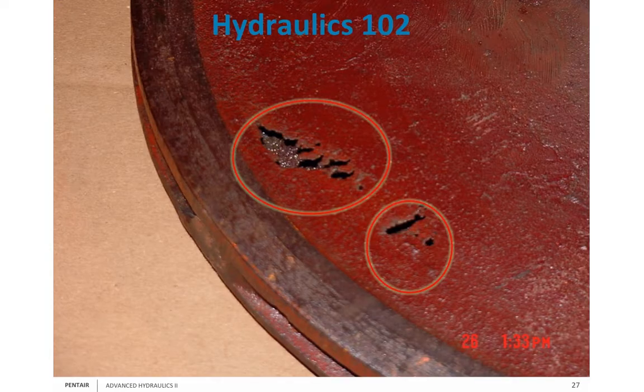Okay? So, cavitation damage here, you can see it's inside those two orange circles. And, of course, you can see it ate right through this impeller. This impeller, by the way, is an 18-inch impeller. It is $2,000 list price. And when we told the customer, look, if you would just slow your flow down, you wouldn't have to be buying a new impeller every year.